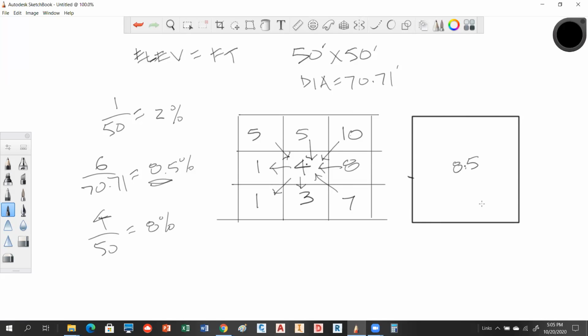Okay. An aspect is referring to the way this guy's locally tilting. Because this is coming in, this is your highest range right here, this is your 8%, then the aspect, this thing would be locally facing or locally tilting in a southwest direction. Because notice this is tilting that. An aspect is important because it has to do with things like the way sun might strike something or the way water would flow.